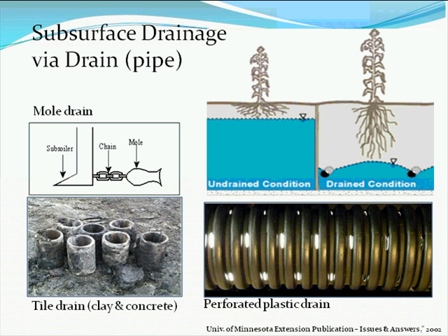Pretty much the practice started with mole drain. I'm sure many of you are familiar with it. It's basically a mole chained to a subsoiler and pulled behind the tractor. That practice is really not supported anymore, perhaps not practiced in many places, but it has some applications. It's relatively cheap. So if you have a field that needs drainage to be installed, perhaps a mole drain can at least drain the soil so one can get into the field for subsequent operations.